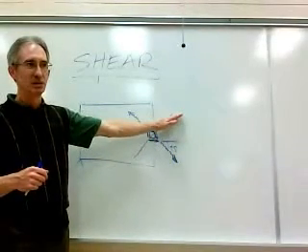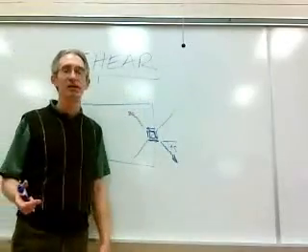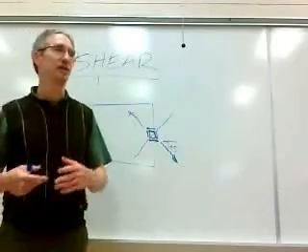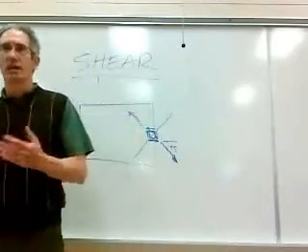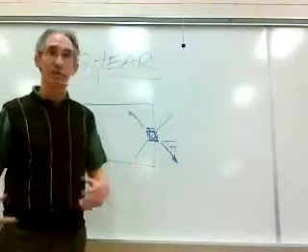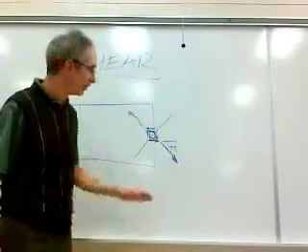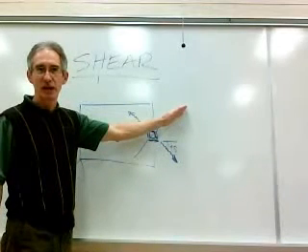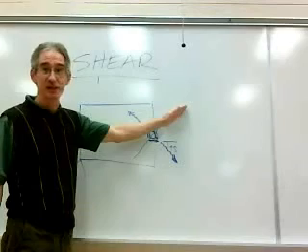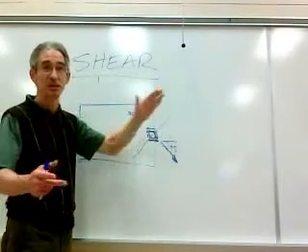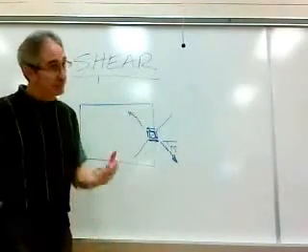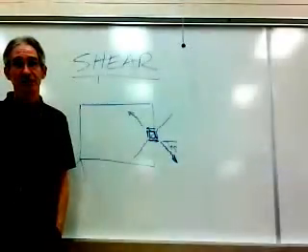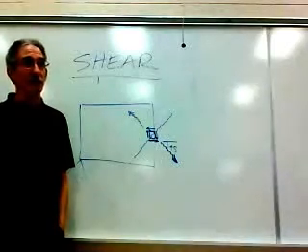If you ever are out there in the field and you've got a project under construction, you've got concrete that's a day old, a week old, a month old, or even if you're in a structure that's 20 years old. Have you ever seen a beam with a diagonal crack in it? Okay? Especially in the regions of high shear, close to the support, that's dangerous. That's telling you something. Okay? That's something to really put up a red flag about.